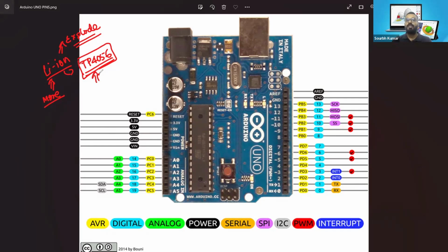Always use a charging module like the TP4056 or any lithium ion charger or any battery charger. That is why manufacturers sell those products in the market, right? If we could charge the battery directly with the pins or the power from another battery, then there would be no need to have those products on the market itself, right?